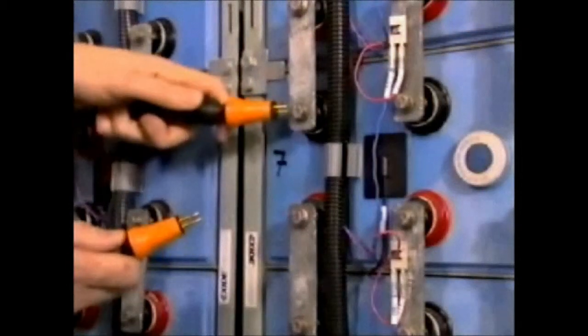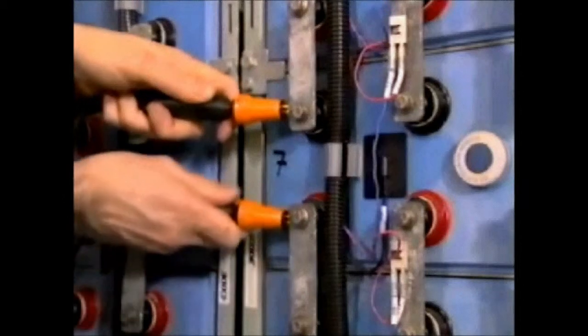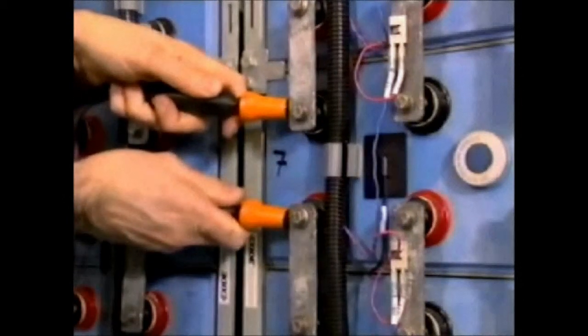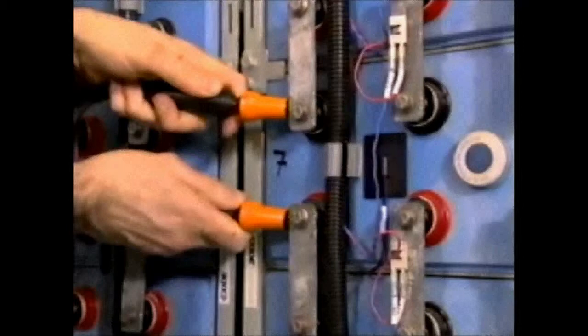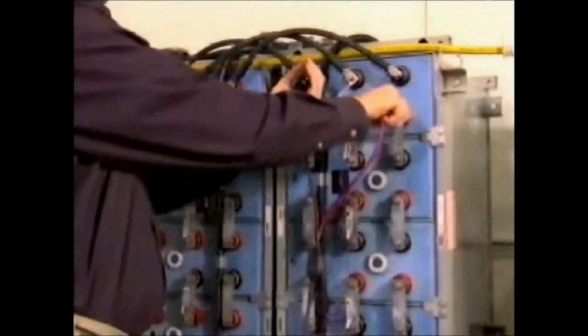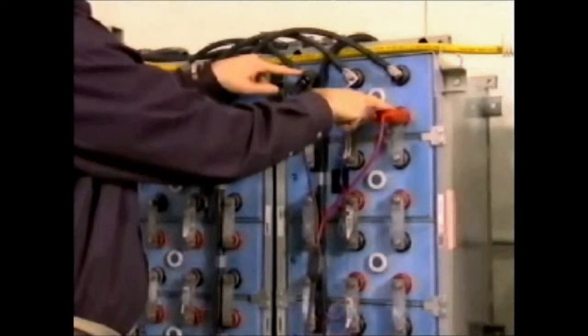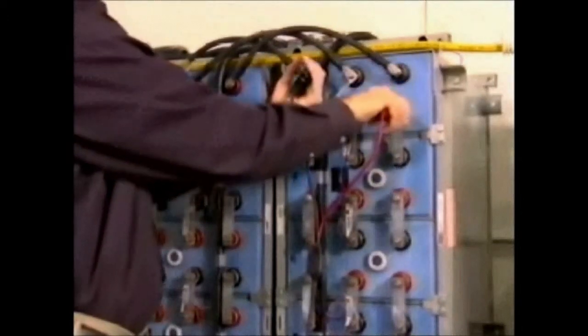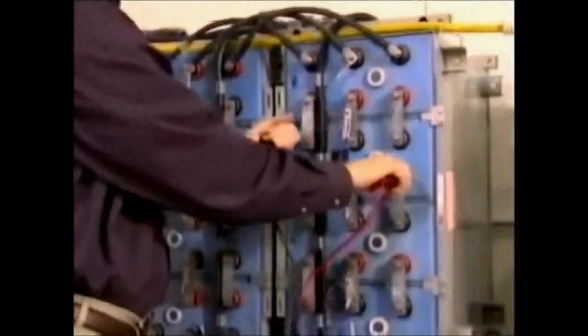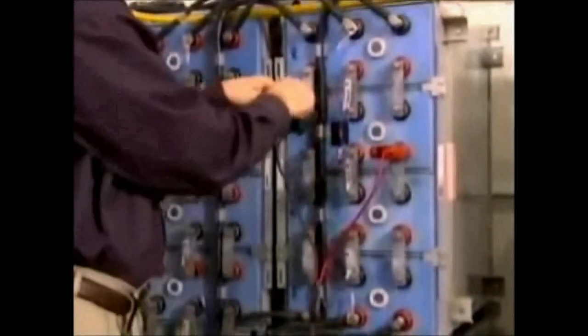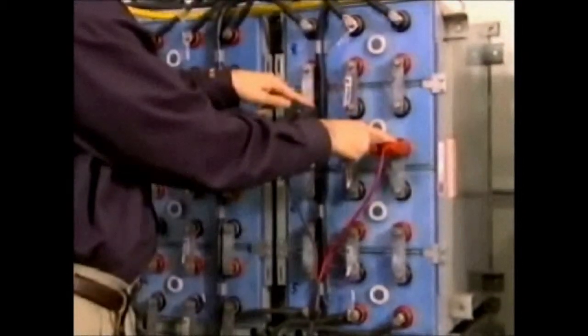One thing to keep in mind is to be consistent. Utilize the same contact points each time. In 4 or 6 post batteries, the common practice is to take one measurement. But if you do it this way, be consistent. Select the same 2 posts each time on each jar. You can also set up the tester for 4, 6, or 8 posts and test each part individually.